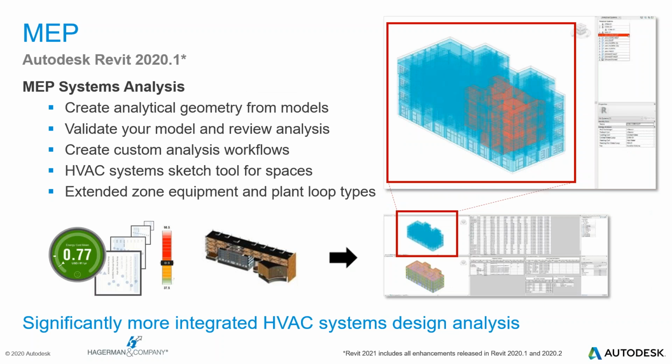Okay, so got another slide or two here. The systems analysis feature in Revit, which extends on the capabilities of Autodesk Insight that leverages location and climate data to perform whole building performance analysis, addresses this challenge by giving HVAC designers the ability to use architectural models in Revit at any level of completeness.